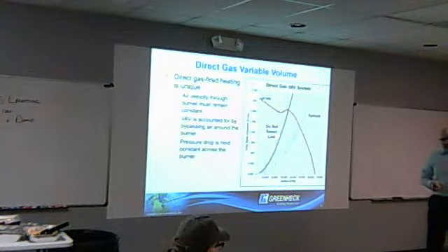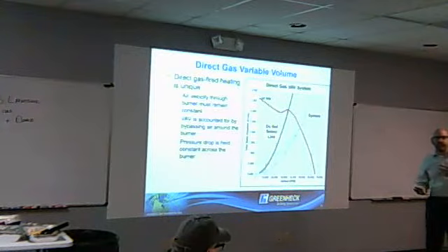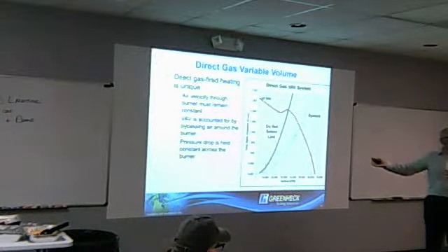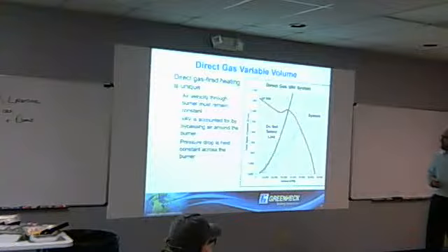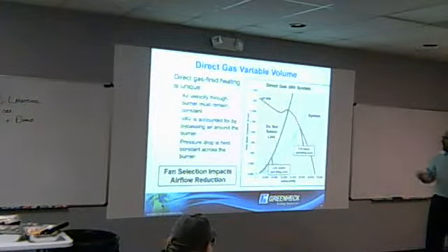Most times I'm talking with engineers about a 50% turn down. They usually come out at 50%. They won't have much need for more than that. But you could, and the other day one wanted to get to like 35%, and we could still do it. The fan curve allowed that. So you're talking about airflow now, not the burner. I know the burner will be adjusted itself, and I think the next slide talks about that.